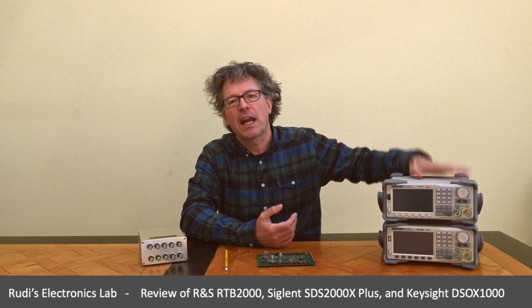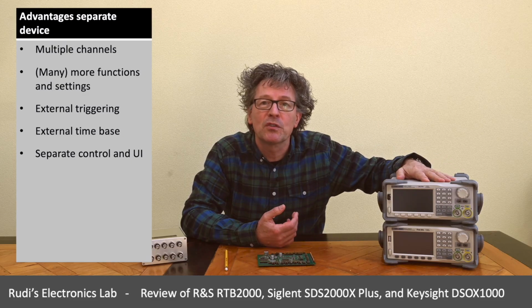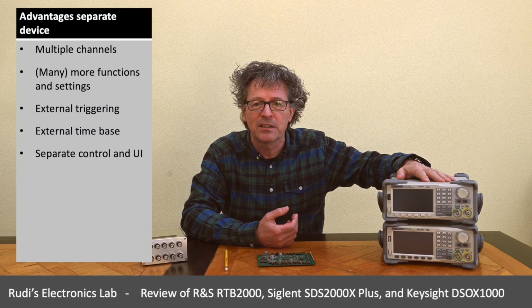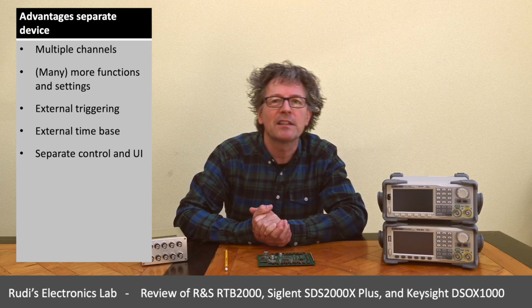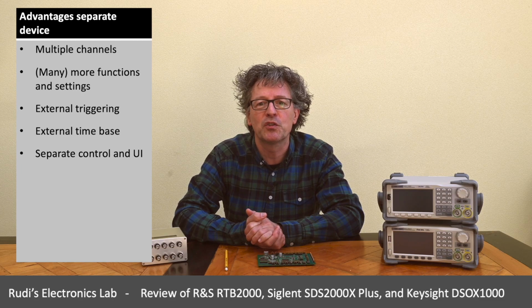Then again, there's also specific advantages related to having external devices like the ones over here. Typically you get multiple channels. The free oscilloscopes I'm looking at today only have a single channel for function generators. Often they have much more functionalities and settings, so they're going to be much more flexible. They would allow you to externally trigger a signal. They would allow you to externally have a time base, a reference time base for the signals that are generated.